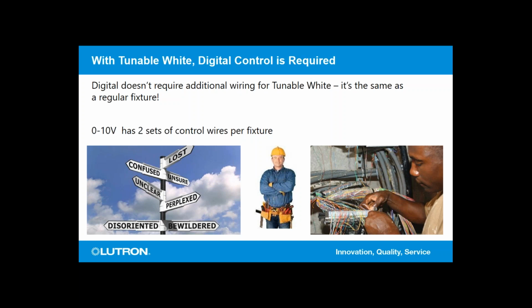Another consideration is the wiring. So there's no change in the wiring with a digital protocol just because you have a tunable white fixture. It's just like a regular intensity fixture. You wire the control wires to it, and everything else is handled digitally in terms of sending information.